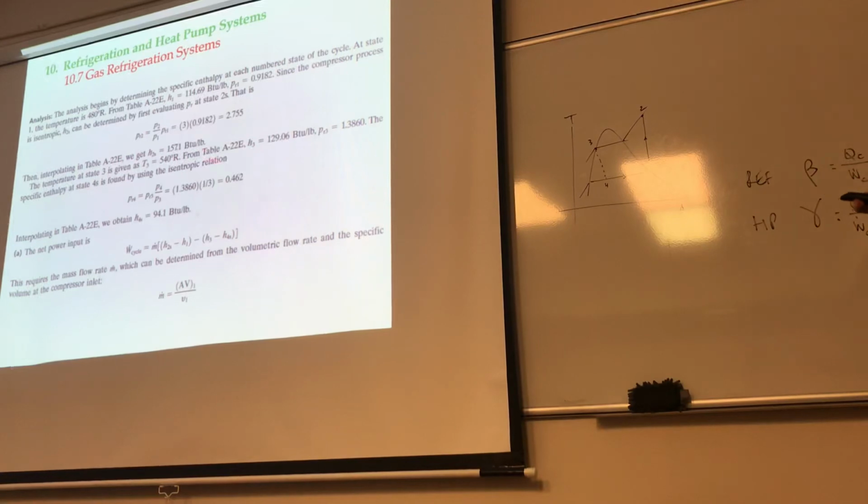Where am I? Oh, 2.755, yeah. So it's somewhere in between. That means the value of H will be between 153 and 157, right? And 157.9. So if you interpolate correctly, you should get something like 157.1. Okay, that's state number 2.